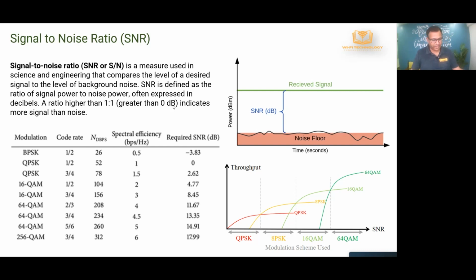Again, if you take this example of this transmitter and receiver, when he's transmitting and he's receiving, they are very close to each other. So the amount of loss of the signal over the air is very less. There are no obstructions. There is no noise. So that means that this guy will receive the signal at a very good signal to noise ratio. Now someone turns on a Bluetooth headset right here in the middle and transmits in the same frequency. Now you raise the noise floor. Now this communication is obstructed. Now this guy has to raise his signal, right?